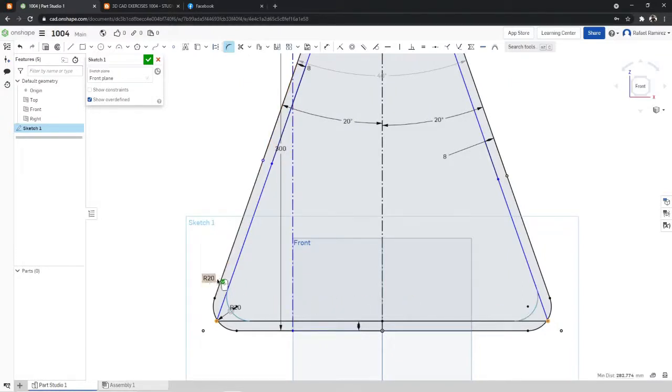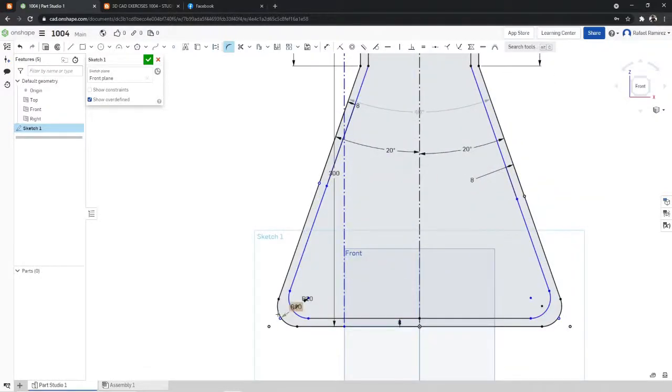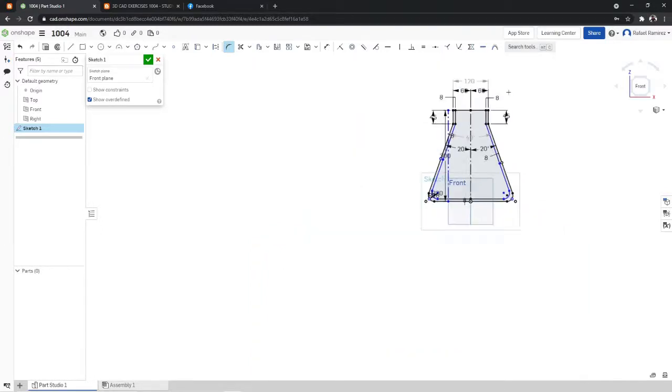As you can see, since we were able to edit the first radius from 60 to 20, the next time that you're going to sketch fillet, it will automatically put in 20 mm there. The most recent number that you have input will be available the next time you use sketch fillet, so you can input 20 mm without editing. So I'm just gonna click on 20 mm. Alright. So these two corners have a 20 mm radius.